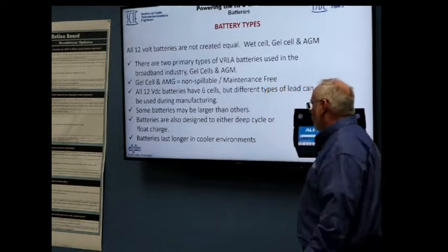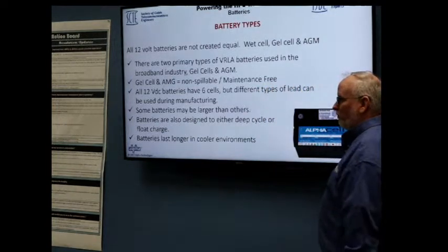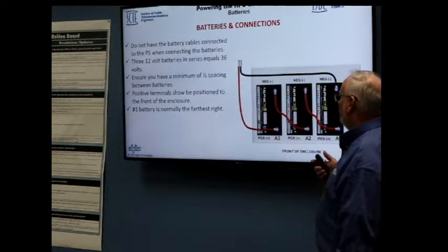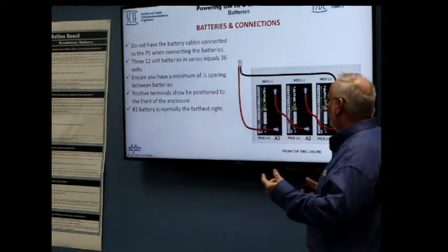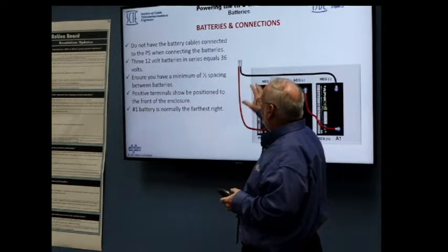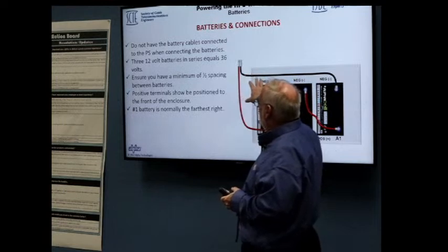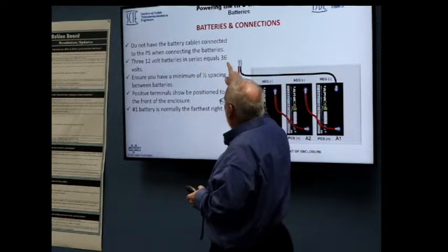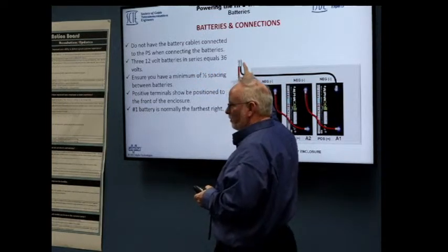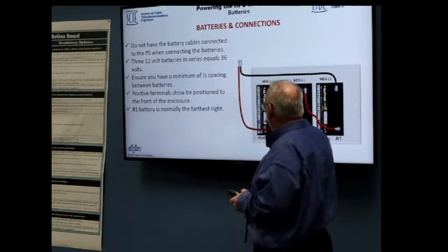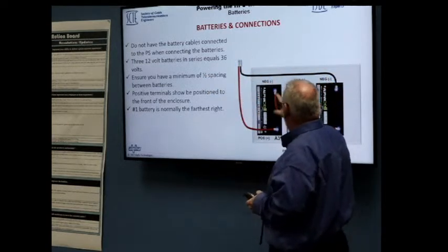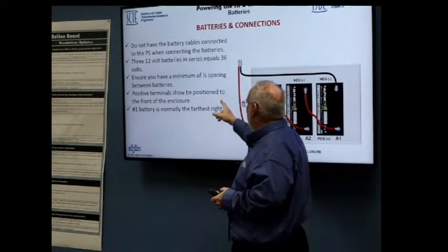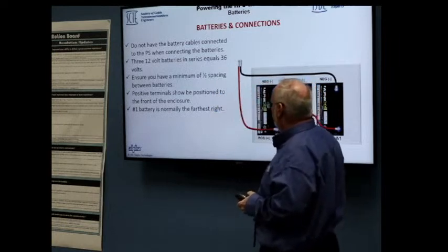Batteries last longer in cooler environments, but they don't do well below 32 degrees Fahrenheit. They lose the capability of delivering energy as they get colder. Do not have the battery cables connected to the power supplies when connecting the batteries. Sorry, I had to say that again. In other words, don't connect these up until all of these have been done. Do that one last. Ensure you have a minimum of 1/2 inch spacing between the batteries.